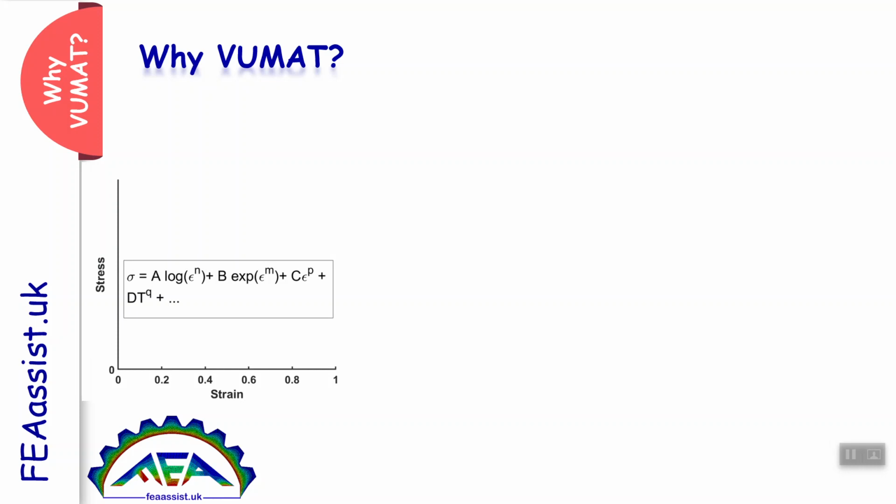But if you have a new equation for a new material, a new constitutive equation, and the equation is not included in Abaqus to enter the parameters and constants, then you will need a place to write your equations and force Abaqus to solve the problem based on your equations. This place is the VUMAT subroutine.